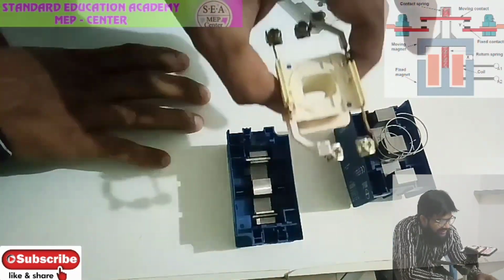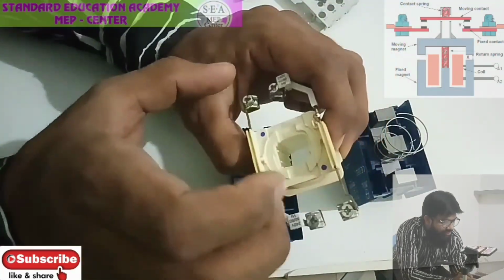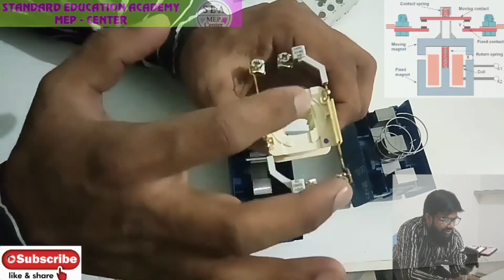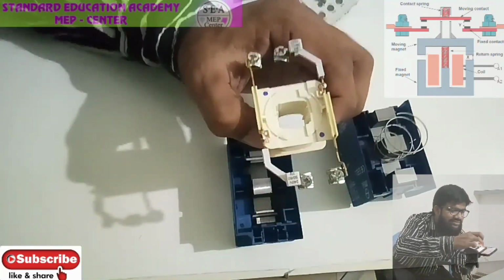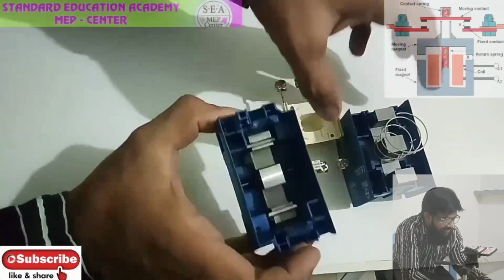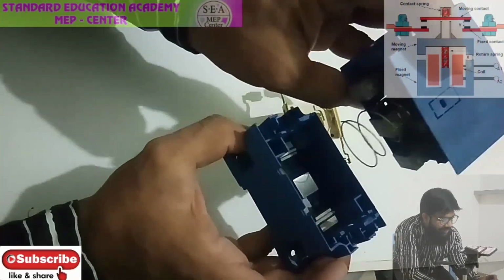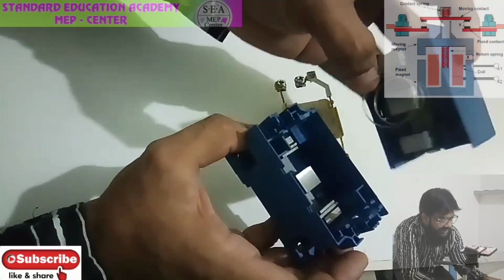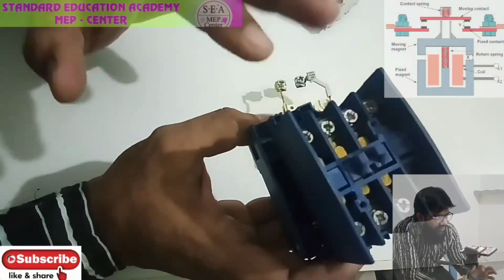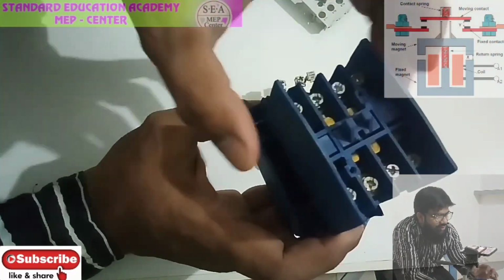As this coil gets energized when we give it a phase and a neutral, automatically there will be a contact between these two particular poles, and due to this contact, our L1, L2, L3 and T1, T2, T3 will come in contact.